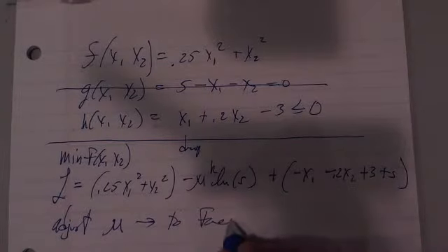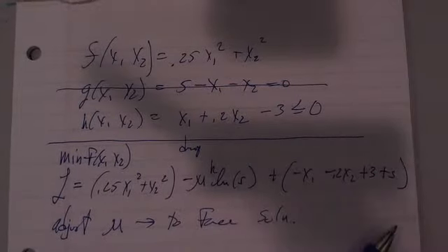to force solution. Now you say, well, why don't we just put the right value for mu in at the start? It's an iterative process, and so you start mu out typically at a value of 1. 1 is always a nice, kind of neutral number to stick in there, and then you get a solution, and then you use that solution as the starting point for the next.